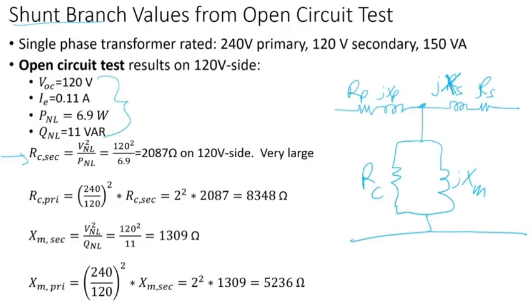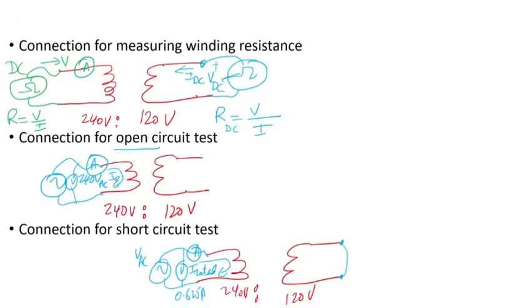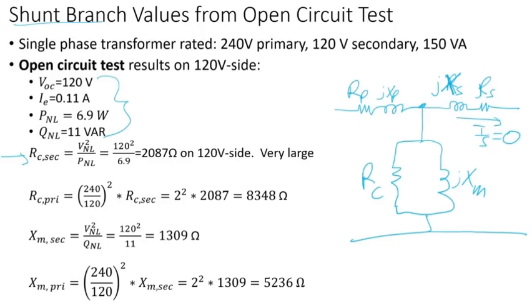When we applied the open circuit test, the current flowing in the secondary, IS, was 0. If I go back to the setup here, since the circuit is open, the current will be 0. However, I applied the test to the primary side, for instance, so some current will flow through the RC, which means the core.